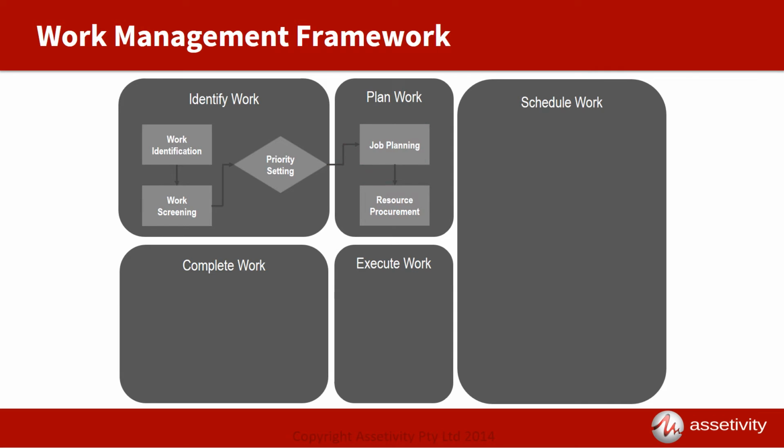Once the work pack has been completed and the parts ordered, the job should be passed to the scheduler to manage. The scheduler will begin with a long-term view of the maintenance department's workload against their capacity and will move jobs forward or backwards in accordance with their priority in order to balance the two. The scheduler may also seek out additional resources from other departments or from external suppliers to deal with unavoidable peaks. There are many options as long as the organisation has a reasonable forward log management process to provide enough time to adjust to workload variations.